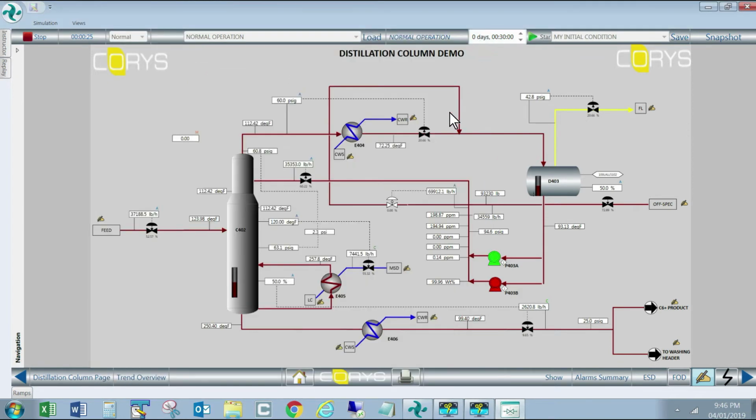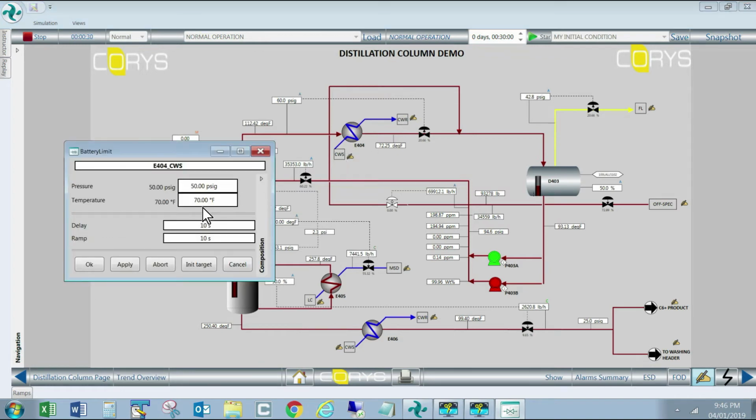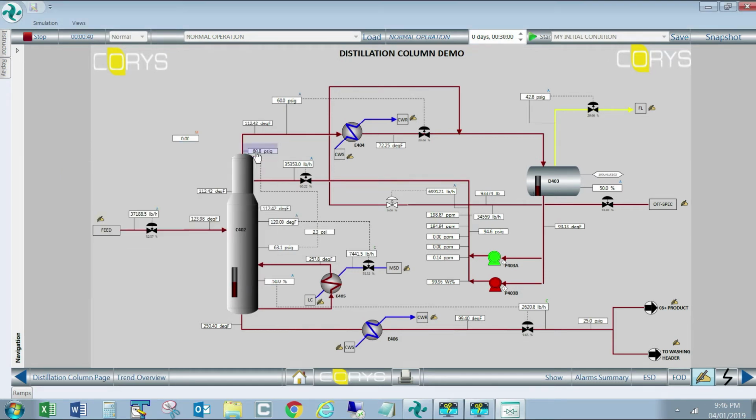He can also change the cooling water supply, pressure or temperature to simulate cooling water failure, complete loss of cooling water or partial loss of cooling water, or the cooling water temperature going up or down. So these can be used to simulate different scenarios, different kinds of upset that might happen in the plant. You can mimic those in the simulator utilizing these malfunctions and instructor variables.